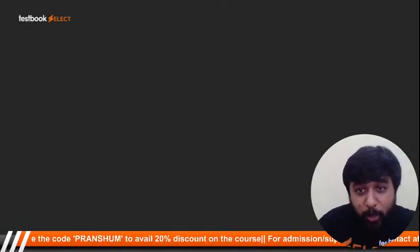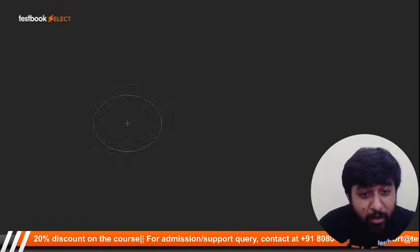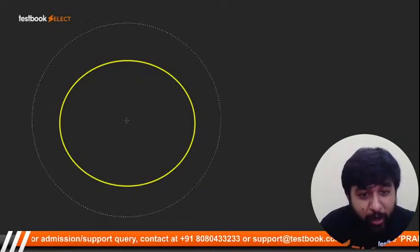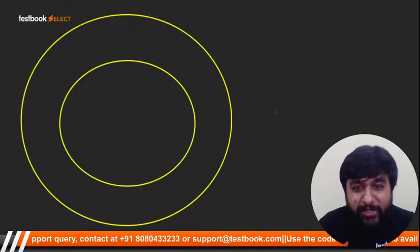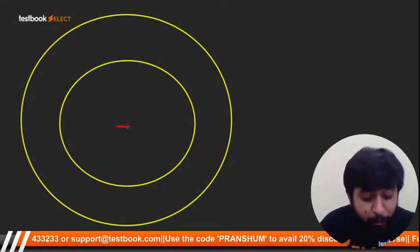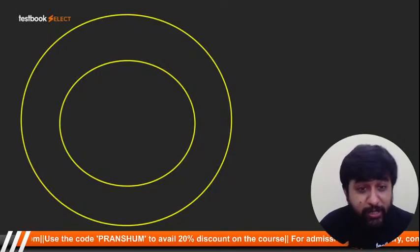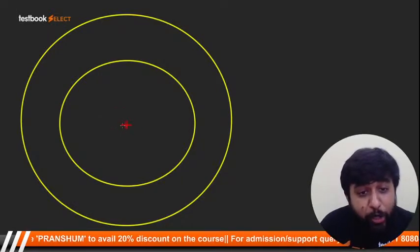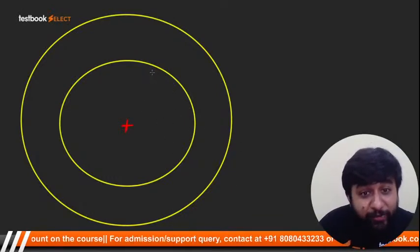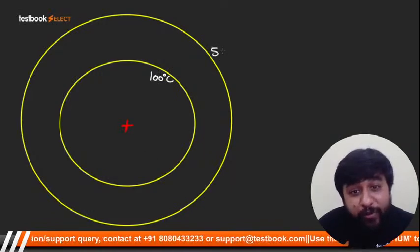So suppose this is the outer boundary of the bulb. This is the outer boundary of the bulb, the glass of the bulb. So glass has some thickness, no? So there will be an inner surface and outer surface. And at the middle point of the bulb, there is a tungsten filament, which is at very high temperature, 2000 degrees Celsius. So that tungsten filament is emitting a very large amount of thermal radiation. Because of the thermal radiation, the entire inner surface is at 100 degrees Celsius and the entire outer surface is at 50 degrees Celsius.